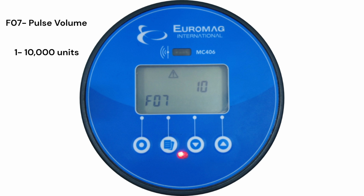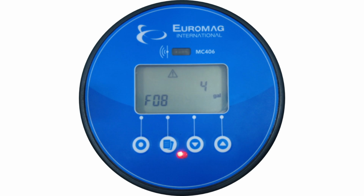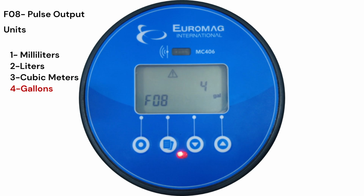Function number 7 is the pulse volume setting. With a value of 10, the converter will send one pulse each time 10 gallons pass through the sensor body. Please select a pulse volume not to exceed 1 pulse per second. Please set the same value in the device the pulse output is communicating to. Function number 8 is used to set the pulse output units. We have selected number 4 for gallons.